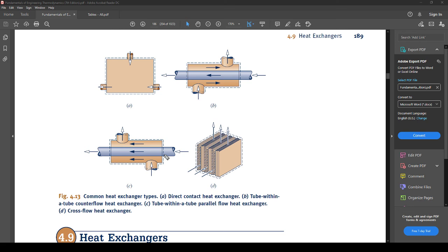So essentially, velocity is something that we can get rid of, because when you enter this device, our goal is to transfer heat, and if you send it through here really fast, it doesn't have enough time to absorb as much heat as you want. If you send it in here relatively slowly, it will, from this entrance to this exit. Now, it also depends on how big your device is, right? If it's a small device, you want it to do multiple passes. That's why I think radiators have multiple passes of the same heat exchanger. But if it's something really big, you could send it through there decently fast, just because of how big the device is, right?